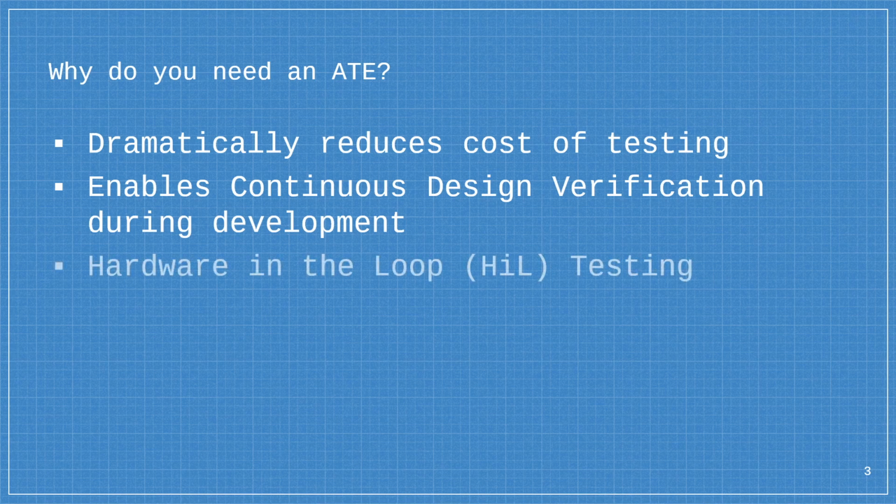If you need to do any sort of hardware in the loop testing, then you're going to need an ATE. And if you're not familiar with hardware in the loop, that's basically you have a set of instruments inside a test rack that are simulating a device that your unit is trying to connect to. So for instance, you may have a flight computer, but you need to simulate the fuel sensor, or you may have a CAN controller that goes in an automobile, like an engine controller, that needs to hook to a simulated engine in order to test it properly.